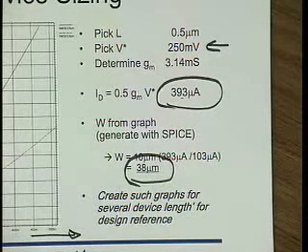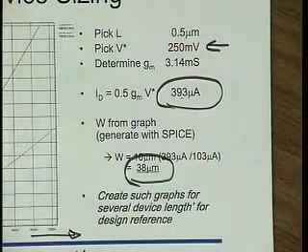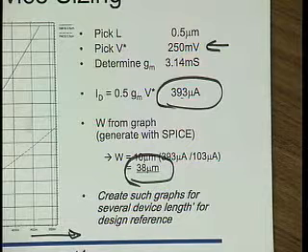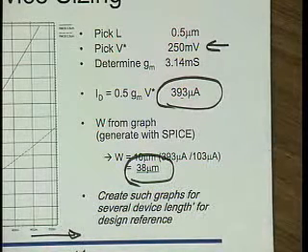Now if I want to know CGS, I can figure that out too, and I can figure out what is VDS and so on. If they're too large, then I have to iterate. But I'm not iterating wildly. I do not pick some widths and simulate, and then it doesn't meet my specs, and then I push another button, and now it meets that spec, but the other one is totally off, and so on. I have a design flow. I actually designed this very simple amplifier.